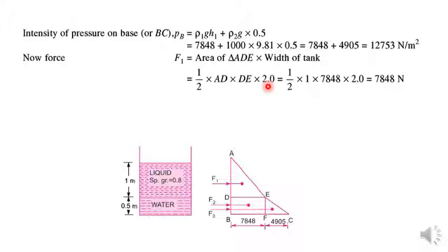In the lateral direction the width has been given. If the total force needs to be determined, then it is not only the answer for the 2D case; you must consider the third dimension in the lateral direction, that is the width of the tank. So for the whole, including the height and the width, you are going to consider the total force exerted on this tank due to this first area.